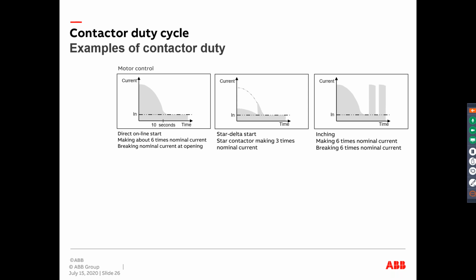One example is that in Australia, in underground mining, we use inching and jogging to start their exhaust fan, which is 110 kilowatt and 1000 volts. It has always confused me that people who do inching and jogging still don't know that they are doing inching and jogging. They still think that it is a dual start. So you need to make sure that if you are repeatedly starting it and giving a break for a few seconds, that means it is inching and jogging, not a dual start.